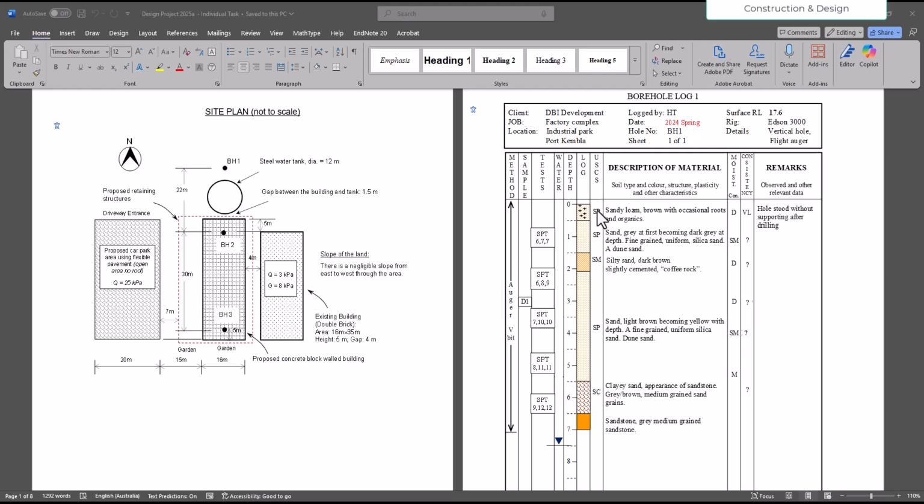Okay, and at each location, as the auger drills from the top, from zero level, and goes down, these are the classifications of soil that it encounters at each level, and this also represents how thick that particular layer of soil is. Okay, and these have to be plotted for some kind of visualization.